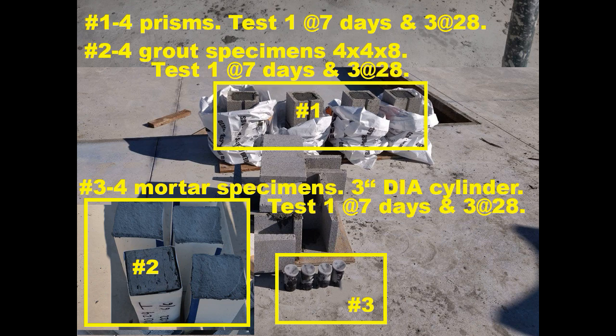Prism tests. Perform at least one prism test sample for each 5,000 square feet of wall, but not less than 3 such tests for any building, typical. Evaluate 3 prisms in each test. Fabricate, store, handle, and test prisms in accordance with ASTM C1314.